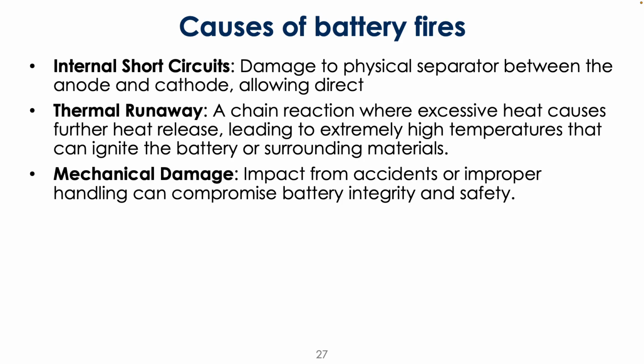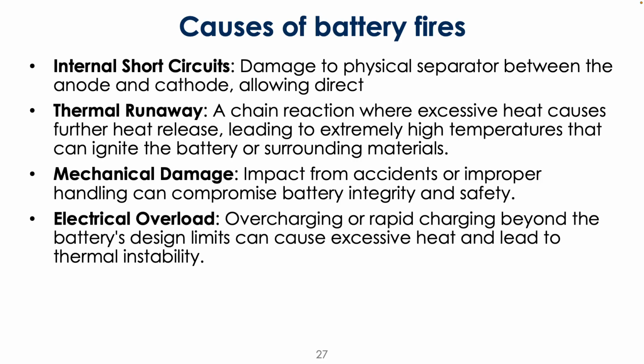Mechanical damage: if you have an accident or improper handling, that can compromise the integrity of the battery. Electrical overload: overcharging or rapid charging beyond its limits can cause excessive heat and then lead to thermal instability and eventually thermal runaway.